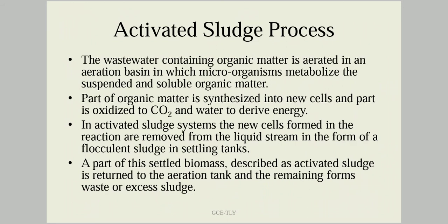The wastewater containing organic matter is first aerated in an aeration basin, and this aeration basin contains microorganisms. These microorganisms metabolize the suspended and soluble organic matter present in the wastewater effluent. Part of the organic matter is consumed by the bacteria or other organisms.